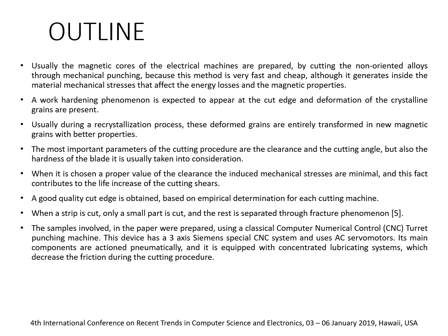When a proper value of the clearance is chosen, the induced mechanical stresses are minimal, and this contributes to increasing the life of the cutting shears. A good quality cut edge is obtained based on empirical determination for each cutting machine. When a strip is cut, only a small part is cut and the rest is separated through a fracture phenomenon.